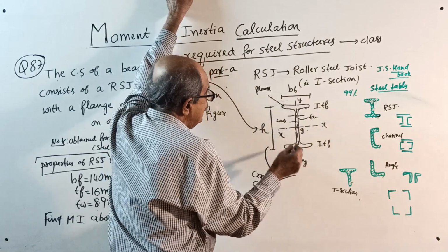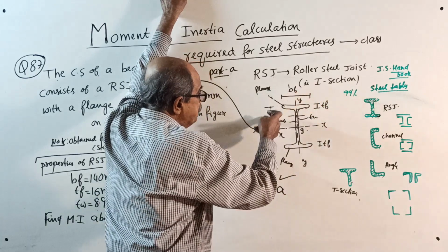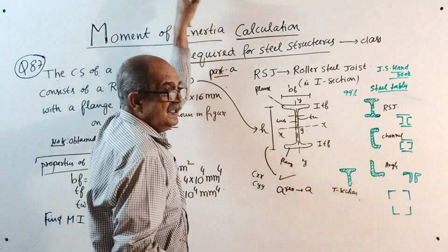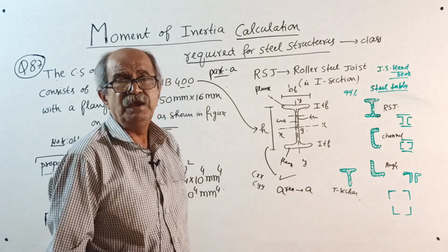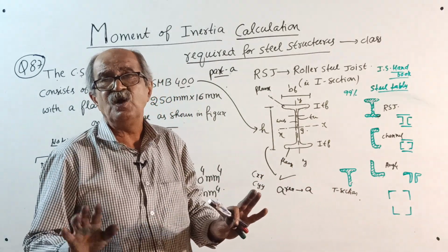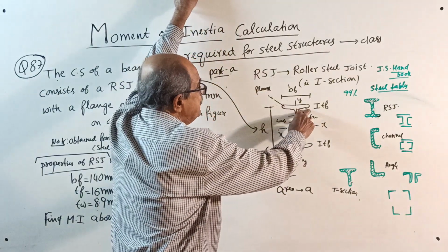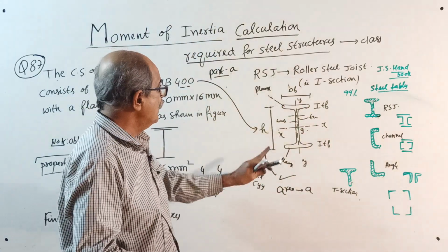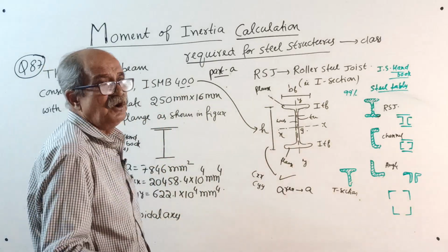Now, in the handbook you can see the moment of inertia about XX, I about YY, and also they will tell you the total area, complete area, symbol A, small a. These values are given considering the curvature. You can see here it is not straight, it is not sharp edges; curvature is there, and they considered it. So you have to accept these values and solve with them.